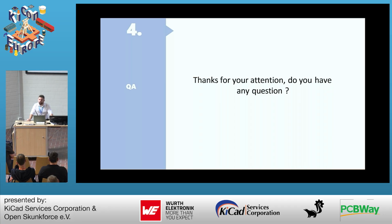We have created a new tool, something like 3 or 4 months ago, to help our customers calculate, regarding our standard stack-up, the width of their lines to match the impedance they want. We have this online. You just have to search on the internet for PCBWay impedance calculator, and then you will have all the values.